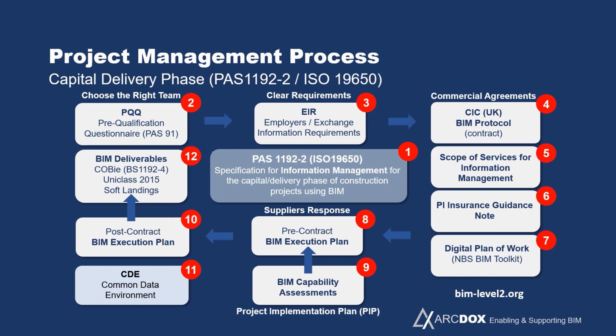So we'll talk about that in a bit more detail. It'll make sure that all the digital objects are classified using Uniclass in our instance, and it may include this soft landings appointment where the team are kept on for 3 years after the handover to do post-occupancy evaluations. But there is a deliverable, and that's the digital version of the building.